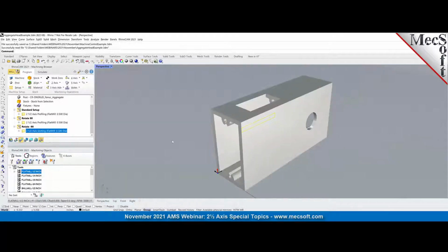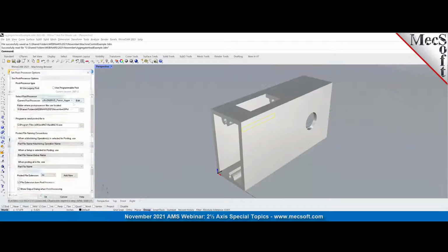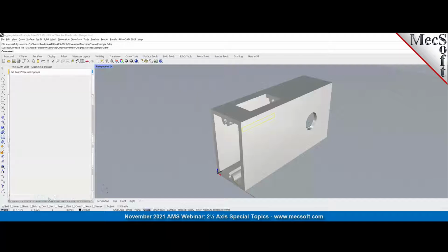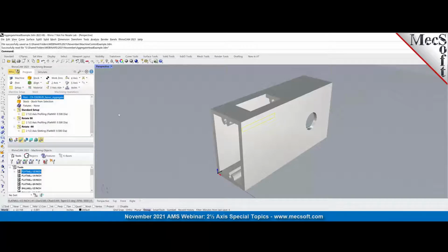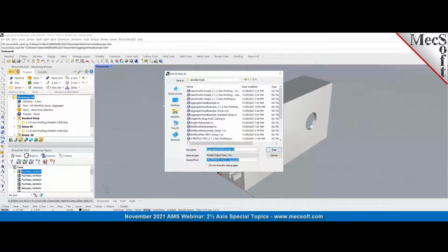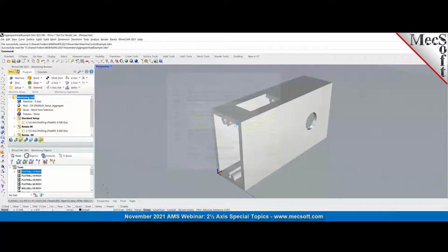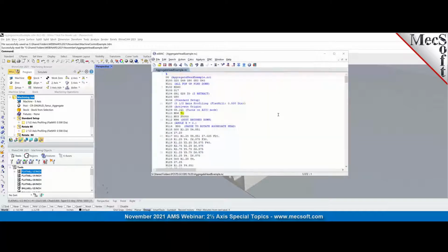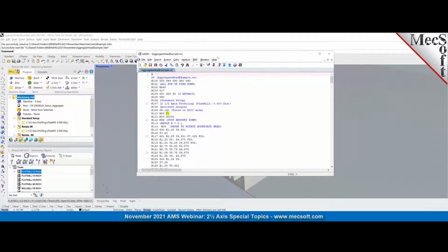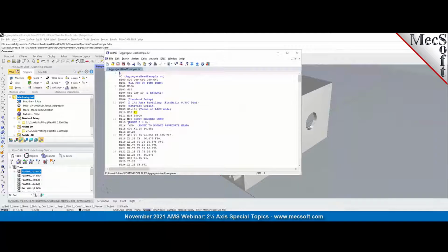And then once we created the toolpaths, we use this post processor, or we could write something specific for your machine, not necessarily this post. So if I go and do a post all, I'll show you the posted code in a minute. So as you can see here, you see the standard setup, the angle we've set up as a B angle to come out as 0.